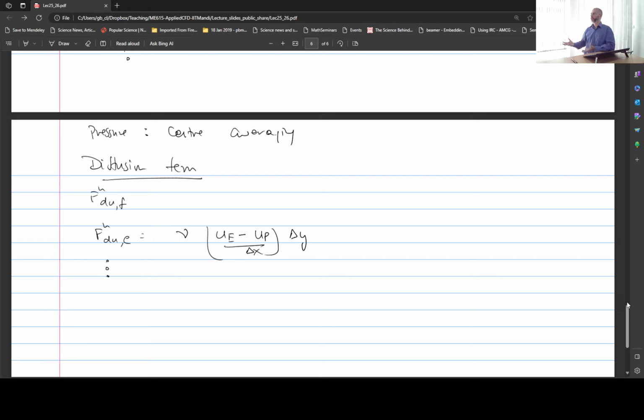So storing the information becomes a tedious task, and when we write loops to loop over all the points, we have to keep revisiting that file where the information on nodal points and connectivity is stored. So that brings in some sort of data structure picture into the algorithm, where you need an understanding of data structures, to know how to store data in an effective way. So you'll see that happening if you work with development of CFD codes, because most of the codes use unstructured grids because of the convenience of handling arbitrary shaped boundaries.